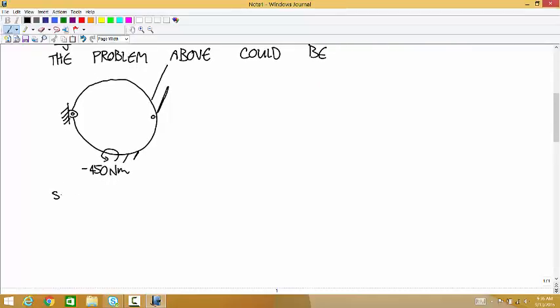Yes? Can you revisit coupling and its equal and opposite? Yeah. Okay, so a couple for us, basically from now on, is just always going to be given as a pure moment. And the way that moment comes about is you have a force going one way and a force going the other way. Like if you're a receiver and you're really unlucky when you catch the ball, someone applies a big force to your chest and someone applies a big force to your feet, equal and opposite, and it creates a big moment.